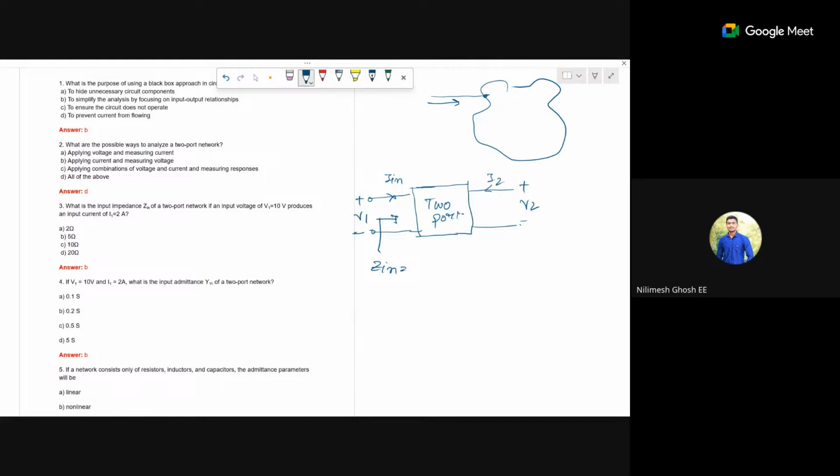You can measure impedance between two points. Saying that we want to measure input impedance from this node is useless unless we have a reference node.